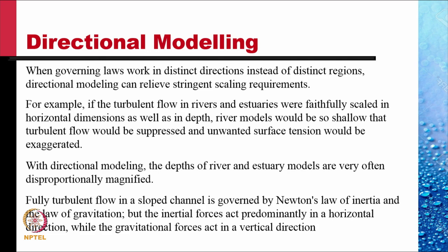Fully turbulent flows in a sloped channel are governed by Newton's law of inertia and the law of gravitation. But the inertial forces act predominantly in a horizontal direction, while the gravitational forces act in a vertical direction. And since these two forces act in different dimensions, we can use different scale factors in the two directions.